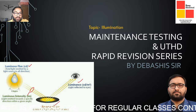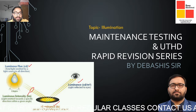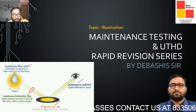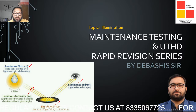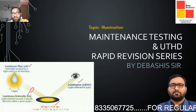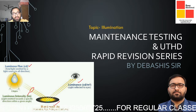Here you find the luminous flux, the amount of light that is getting emanated. Luminous intensity, the amount of light that is coming out in a direction. The amount of light that is falling on the surface per unit area is the illuminance. And the amount of light that is accepted by the eyes, after reflection, is called the luminance, in candela per meter square.